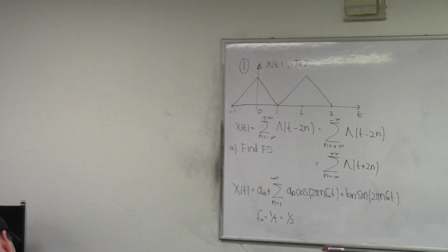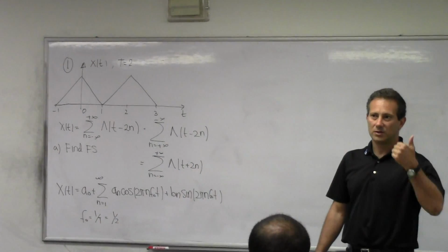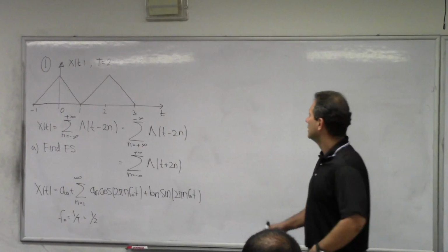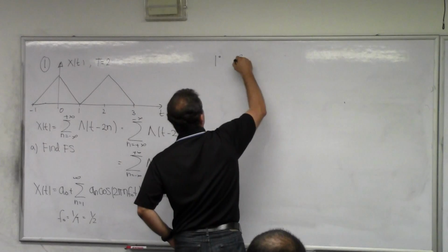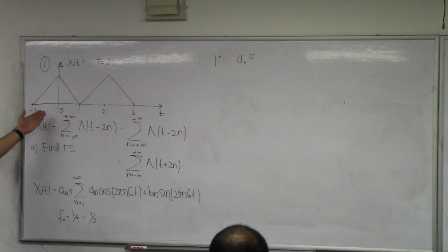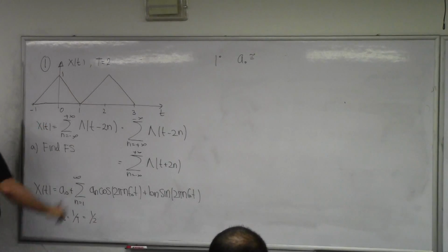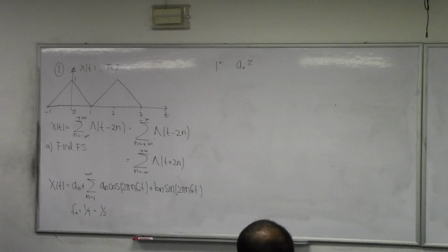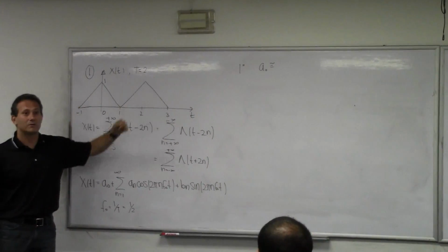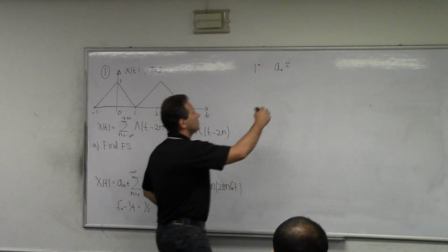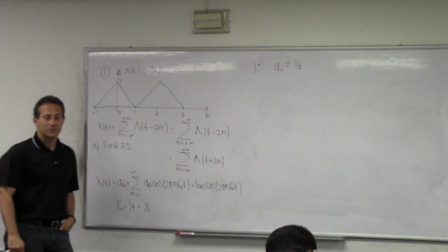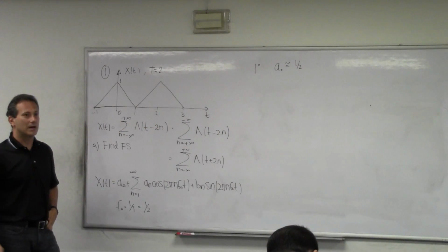And we've seen that calculation of these things has 3 parts. One is you calculate a0, and calculate an, and calculate bn. So the first thing is I calculate a0. And the first thing I want you to do is eyeball this and tell me how large is a0. 1/2. Do you all see that? Yeah, average value is about 1/2 at least, right? So you can say it should be around 1/2. It's a DC value also. DC value, average value, that's all the same statement. So a0 should be 1/2.